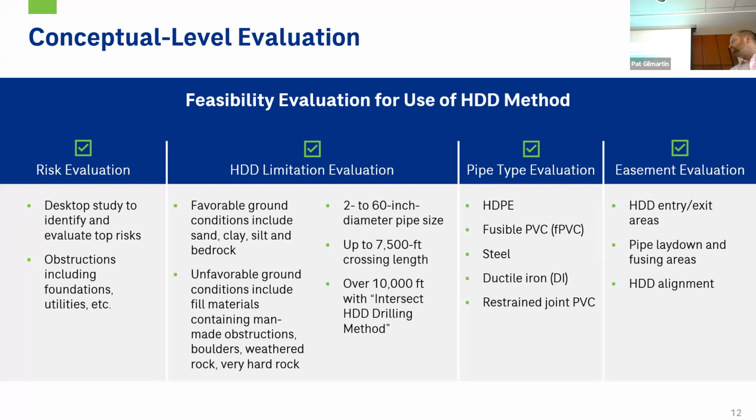And then when you get into truly hard rocks, like you get over in the mountains and in the Appalachians, once you get above about 30 KSI or 30,000 PSI rock, HDD becomes a very difficult technology. It becomes extremely slow moving. And so a lot of times your tunneling methods like microtunneling or pipe jacking or hand mining end up being quicker than the HDD, and actually more cost effective for you.